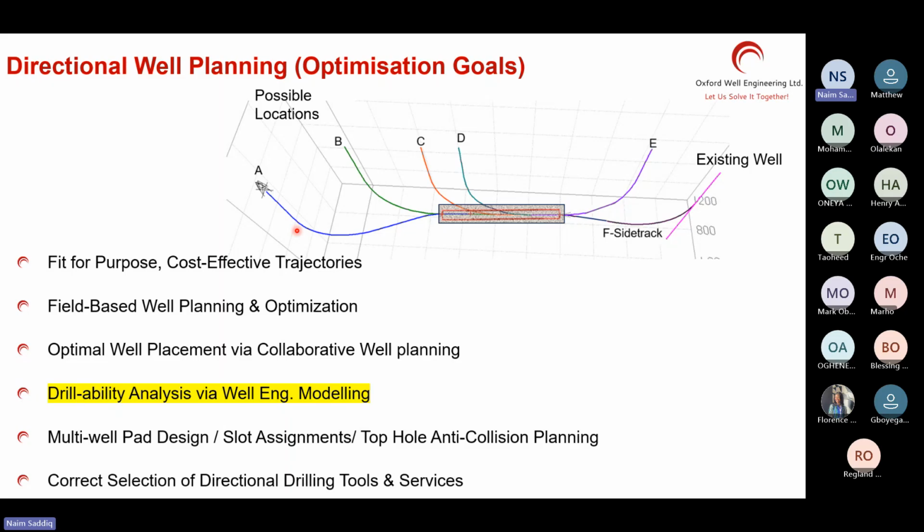Are the ECDs going to be okay? The BHA they are planning, can we use the BHA with this plan? It's very, very important to put two halves together. One half is what they have been writing in the drilling program. Would that fit with your trajectory? The mud weights and the BHAs and the drill pipe, would that match up or not? That's the important part right there.